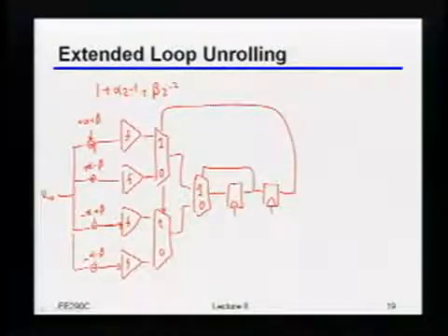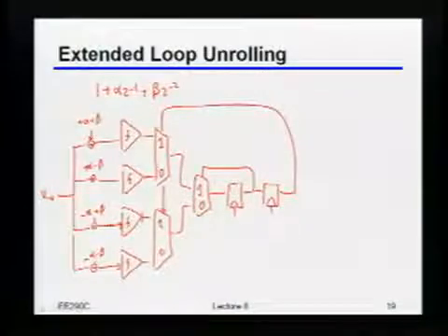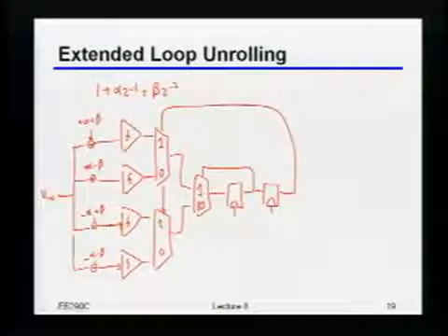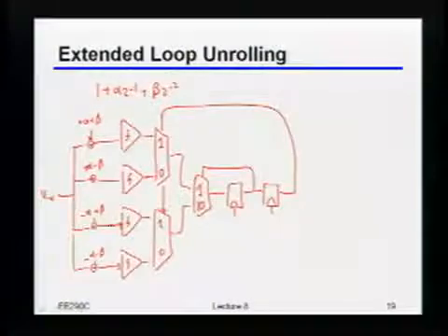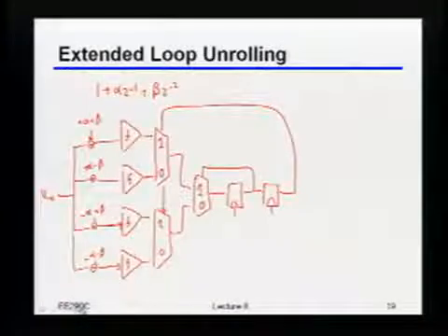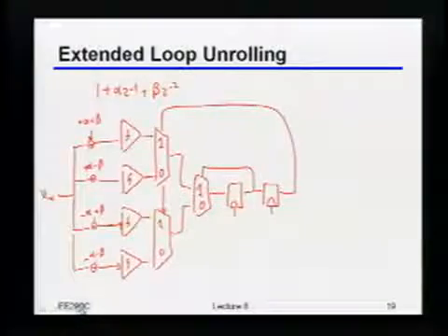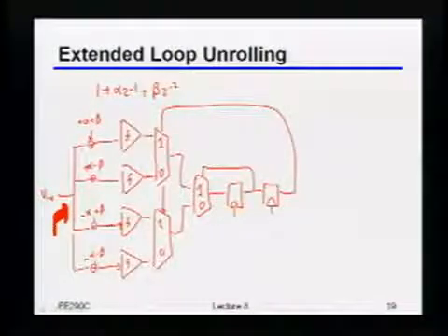Okay? So indeed, this works. And by the way, you can even push this one flip-flop around a little bit if you want to, as long as you don't need that information to close the next tap. So in other words, you can actually pipeline this thing a little bit. But again, most practical designs, if they do any loop unrolling, usually only do the first tap. I think only recently people started doing the second tap, but I'm not sure. I'm not really convinced that that's a worthwhile endeavor because, remember, all the power that you spend for everything in front of it is proportional to the amount of capacitance you've got here in the first place. And so 4xing the number of comparators pretty quickly adds up from a power standpoint.